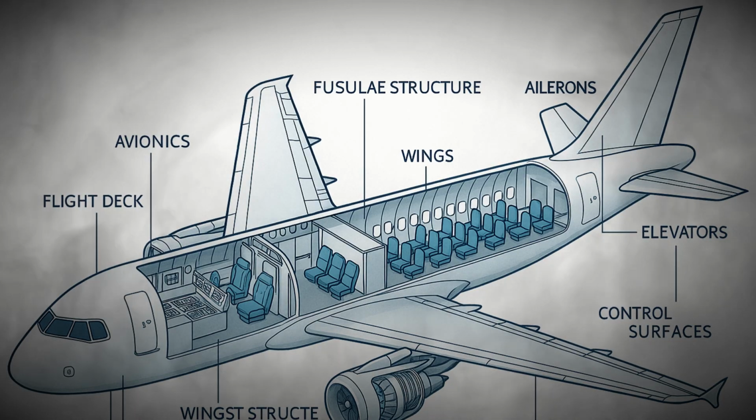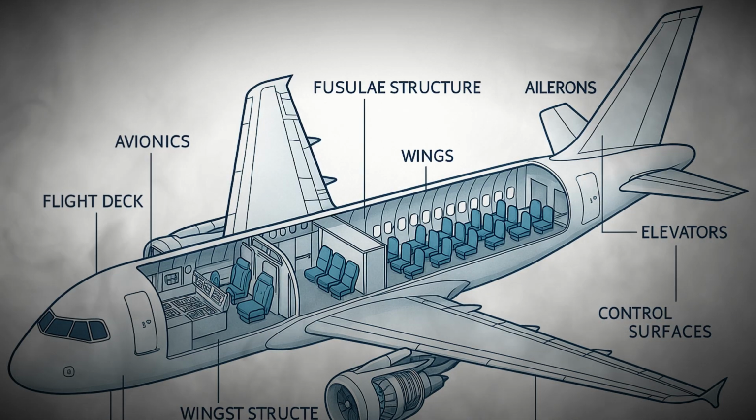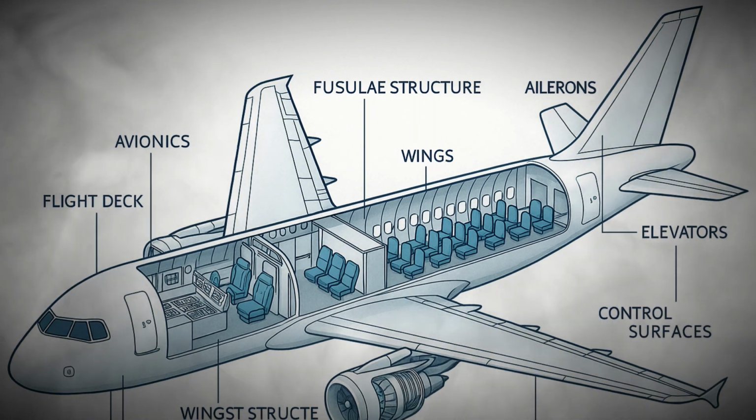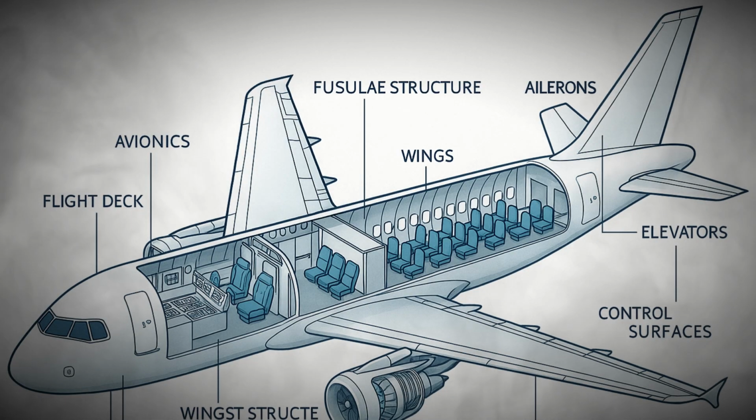The altimeter displays altitude by measuring air pressure, while the airspeed indicator shows the speed relative to the surrounding air. The heading indicator works with a magnetic compass to give direction, and the vertical speed indicator shows the rate of climb or descent. In modern cockpits, these instruments are often integrated into digital displays known as glass cockpits, which replace many separate dials with multifunction screens. These displays can be customized to show different types of information, reducing clutter and improving situational awareness.